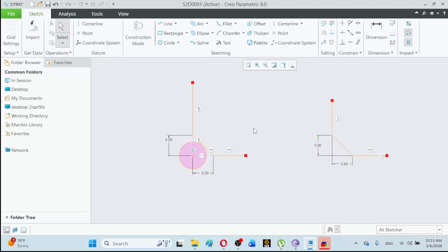So the main difference between the chamfer and chamfer trim type is, in the trim type the original traces are actually vanishing or disappeared. These are not existing, these are not available. But in the simple chamfer type, the original traces of the original line segments are available.